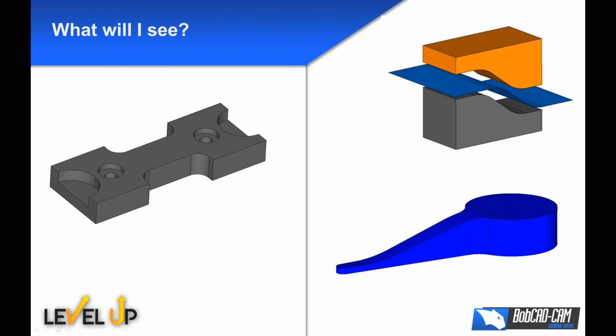Here are a couple of parts we'll see in a couple of examples. We'll create something like this part here on the left, this gray one, using extrude boss and extrude cut, again something that's commonly used. The split function, top right, is something where you can take a surface and split an existing solid. Really useful function there. We'll be looking at another example of an extrude boss and cut, to get what looks like complex geometry, but is quite easy to do with the functions. The idea today is to go through each of those. And again, if you guys have questions, just let me know.